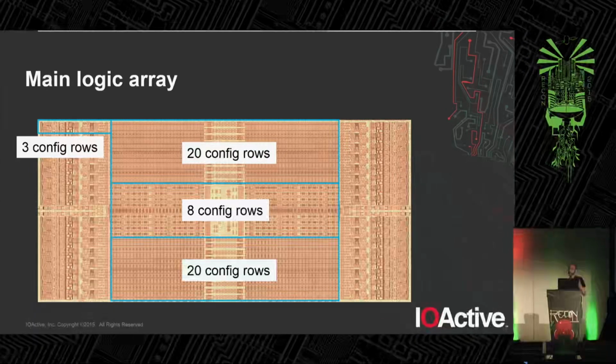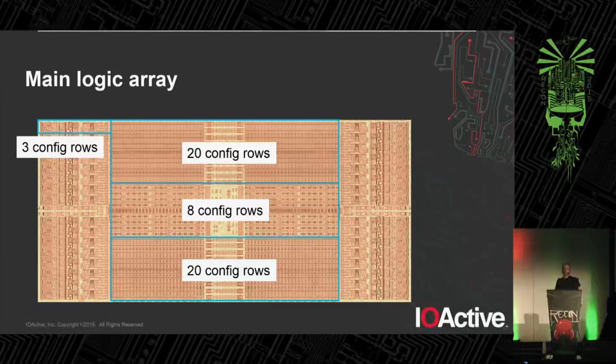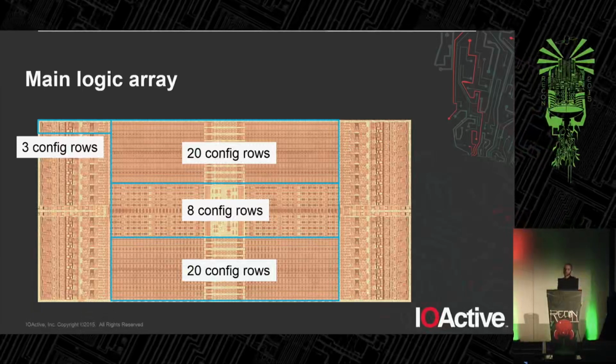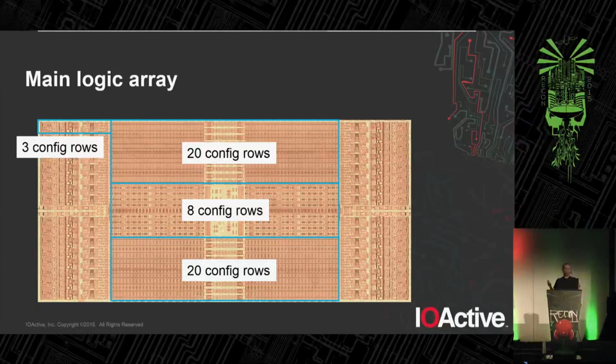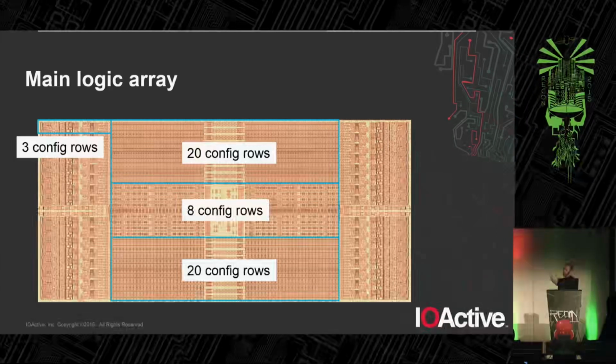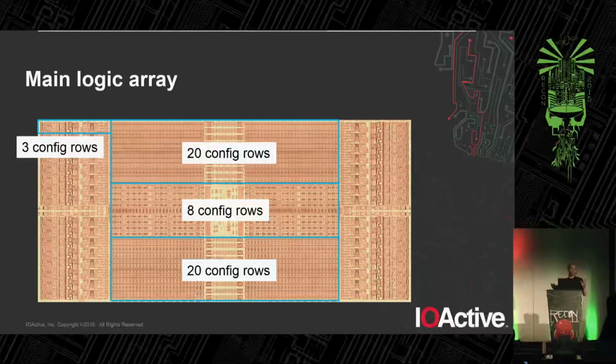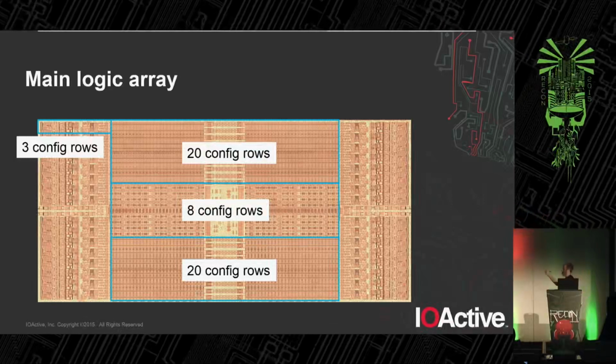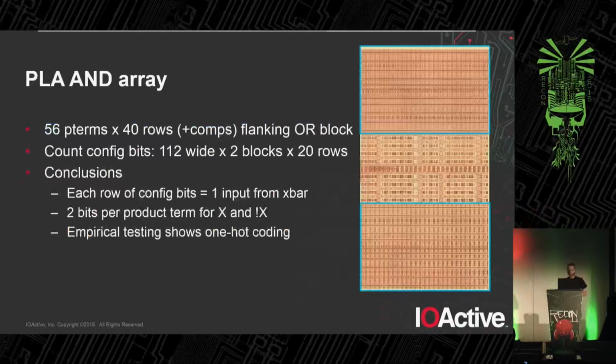And we can make a pretty good guess that since we have a 2D SRAM array here in the configuration area, and we have a 2D flash array, we probably have either top to bottom or bottom up addressing. There's actually some gray code going on. It's a little more complex than that, but logically, we should have the addressing going across vertically.